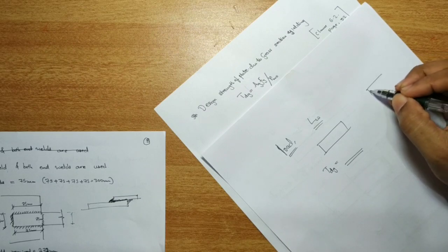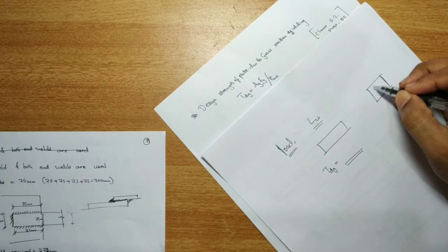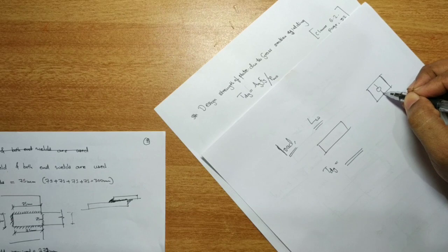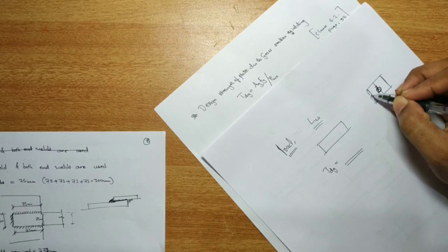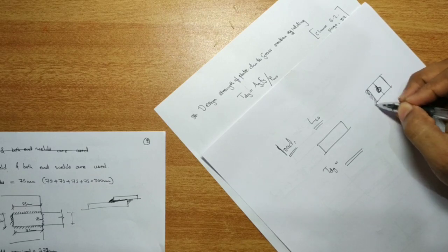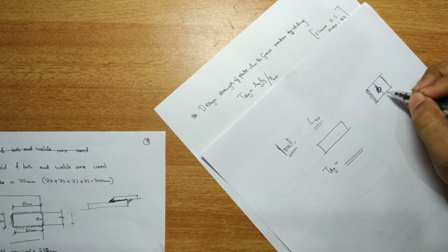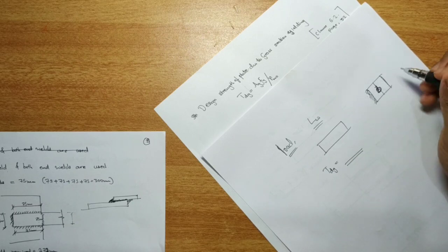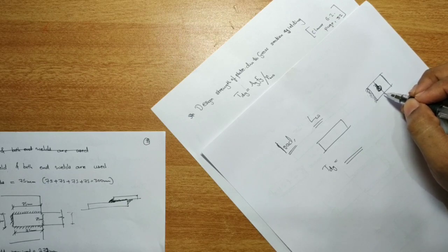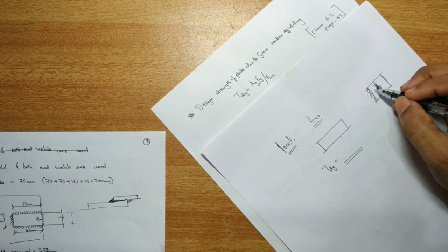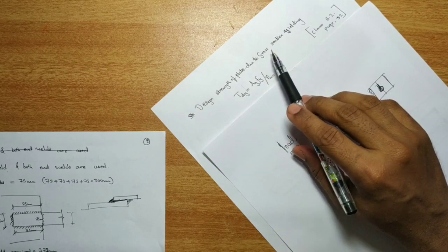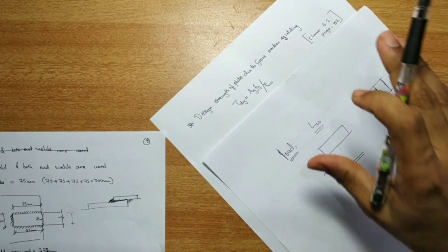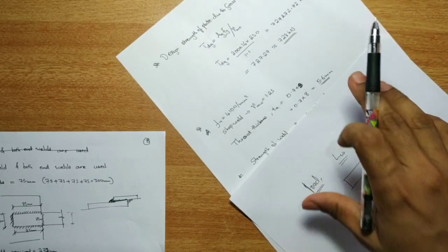No need of calculating the net area because it is not a bolted connection. No area is lost here, no area is lost due to any holes. Here, another advantage of the welded connection is that no area is lost. The complete area is taken to carry the load, no concentration of load. So no need of calculating any net area. You need to take the total gross design strength of the plate due to gross section yielding. That strength you will be taking as the strength of weld.